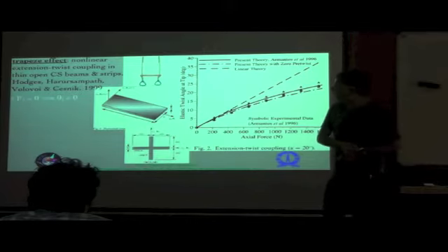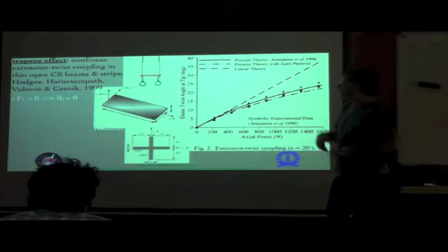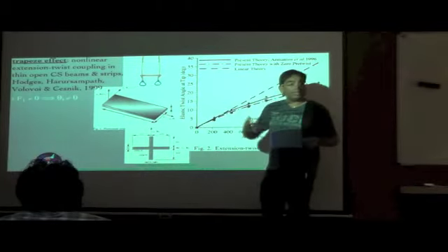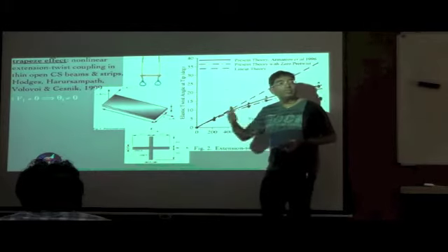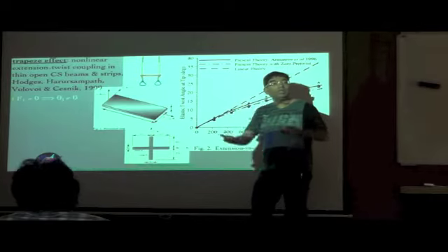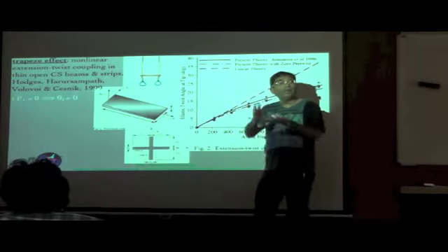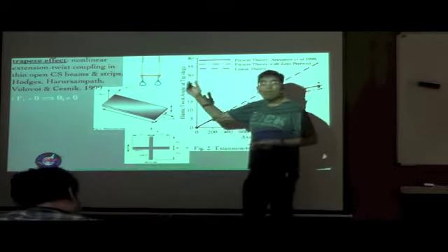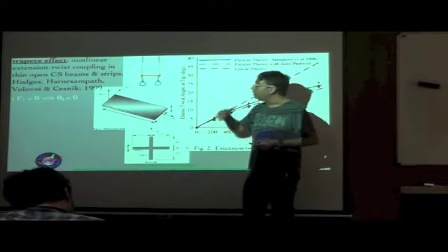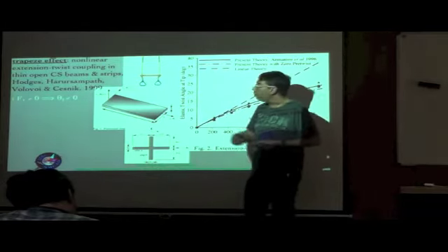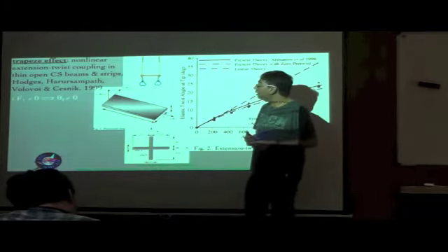So what actually happens here is you have a non-zero value of the axial force. In all these cases, F's represent the force and M's represent the moments. Both are internal, or in other words, they are the reactive behavior at any given reference cross-section. And the components 1, 2, 3 represent the components along the respective directions of B1, B2, B3, as we have been discussing earlier.